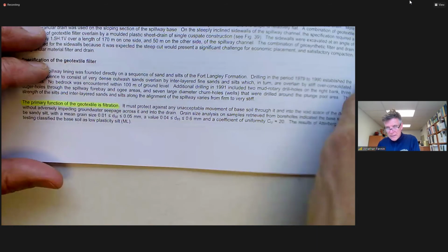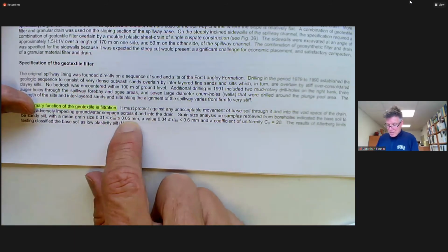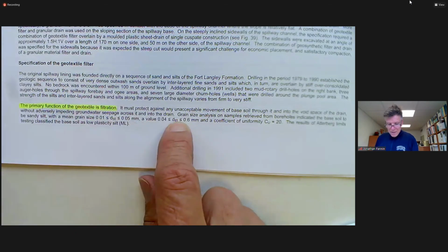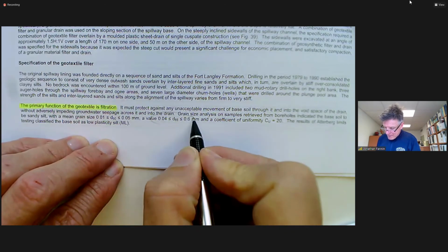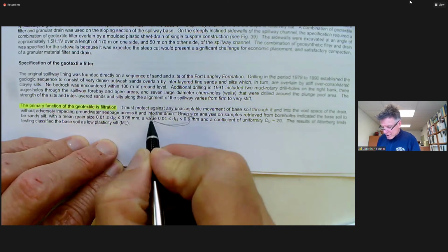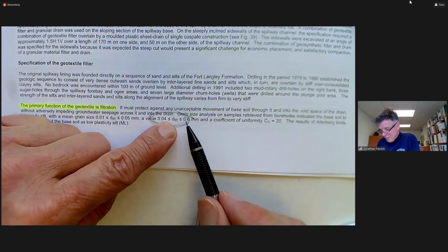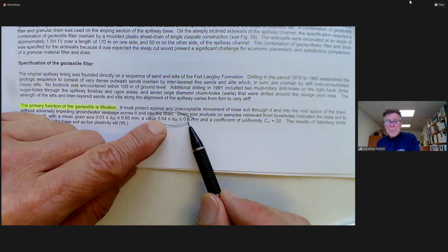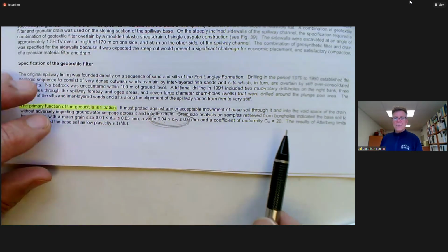It's a sandy silt, and actually probably quite similar to some of the Port Coquitlam area. Medium grain size between 10 and 50 microns, so that's quite small. And then this very large range in D85. So that was the first challenge I was working with: wow, am I going to design a geotextile filter for a D85 of 40 microns, or am I going to do it for 0.6 of a millimeter? That's an enormous range. And a coefficient of uniformity of 20.